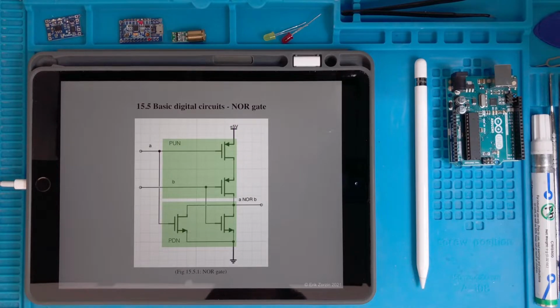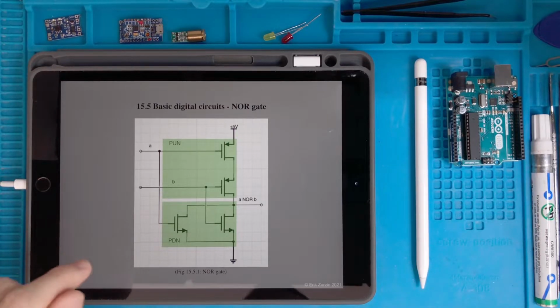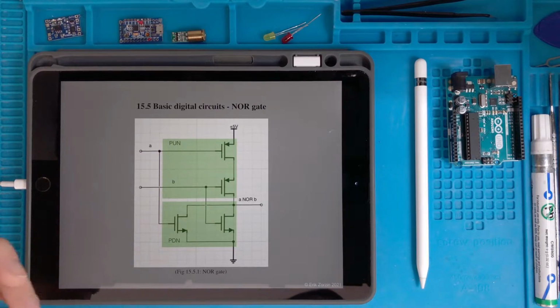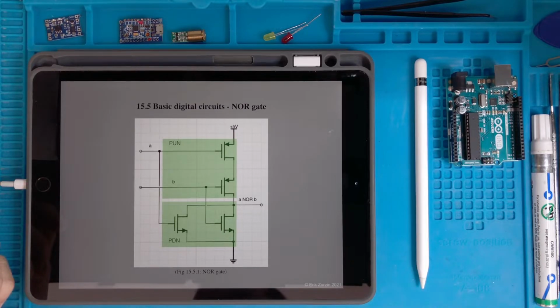And it can be demonstrated that once you have an AND and a NOT, or an OR and a NOT gate, you can create any logic just by combining those elementary circuits together. It's like when you define multiplication, division, subtraction, and the other fundamental operations, then you can do any other calculation. It's just an application of many of these elementary operations.